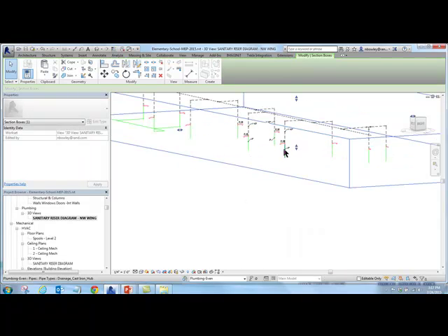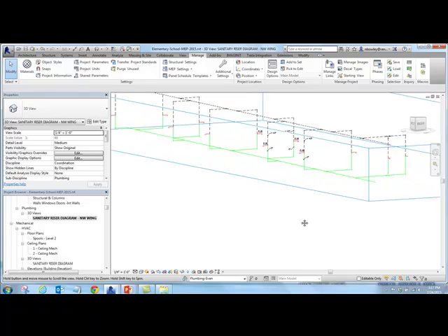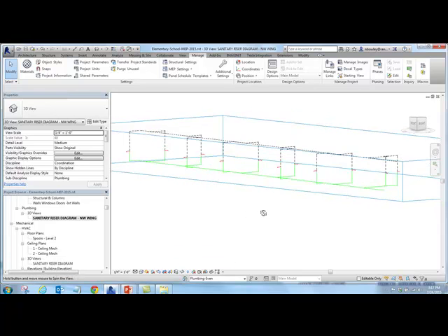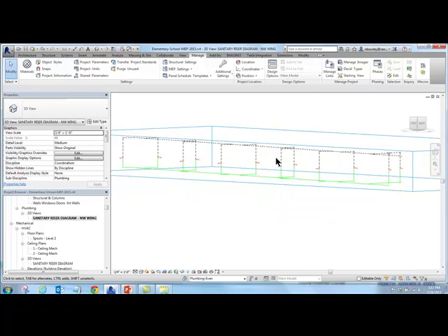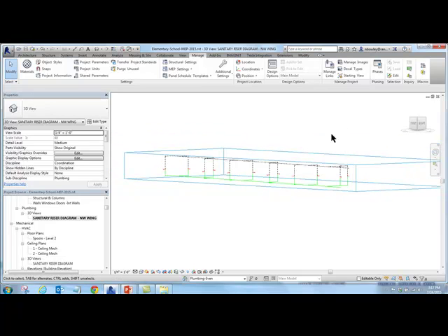So what I might suggest, and I'm not saying this will be easy. I'm not going to be one of those people that pretends that they work that well. But that allows you to isolate part of a building, and then, you know, if you have to unlock the view and you're trying to get that view looking the way you want, it allows you to do that, but you don't have all the other floors. So if I was doing that, this is the second floor, but if I rotated it like that, I'd probably be catching the first floor in another wing in that same area.